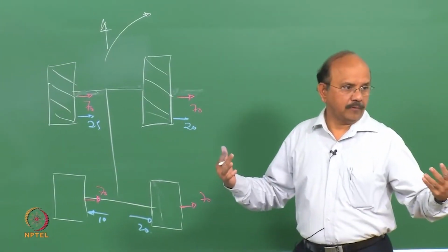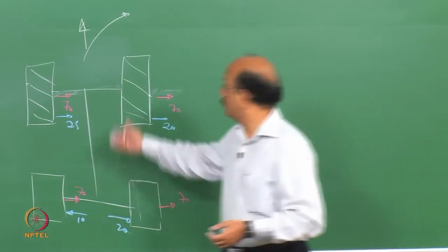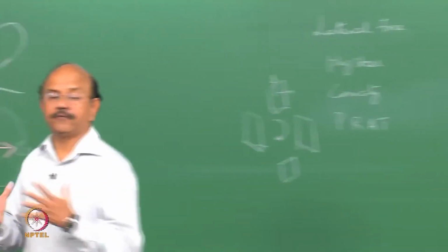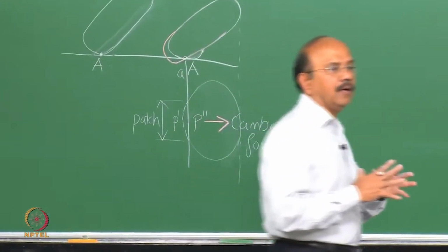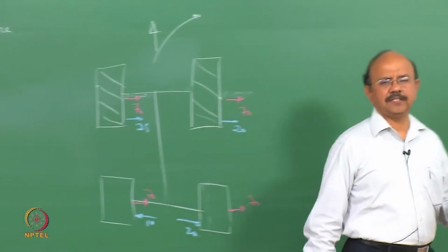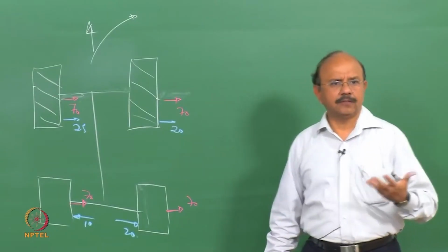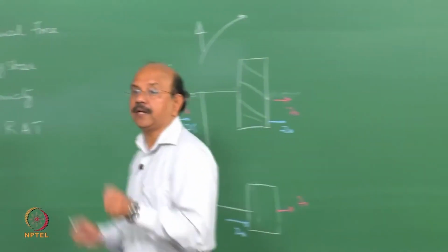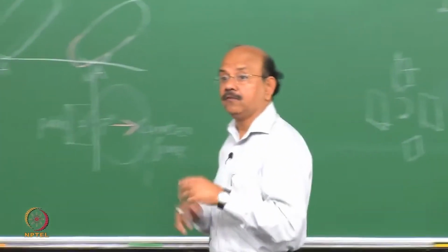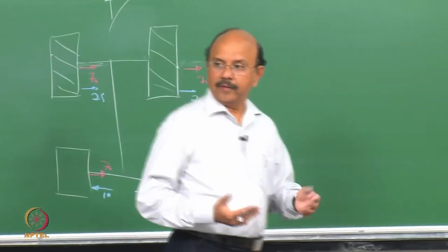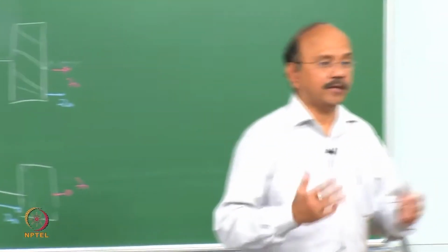So you have to constantly steer the vehicle in order that it goes straight when these force distributions are not uniform. One of the things that you can do is to actually shift the tires so that this kind of distribution is not bad. You can eliminate it completely, which is difficult, but at least you can make it small. But what's the effect of this? The effect is obviously that I'm going to constantly steer the vehicle, which means that an opposite force has to be generated, which means that there will be a slip angle, and hence there will be wear.